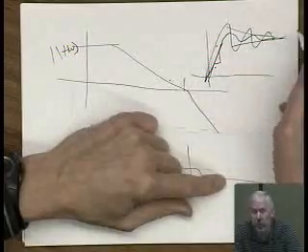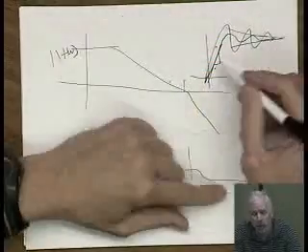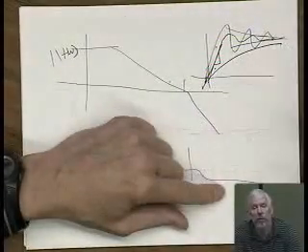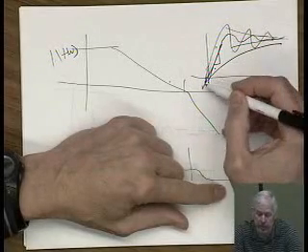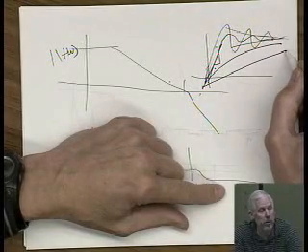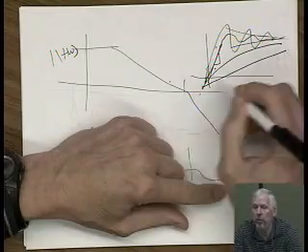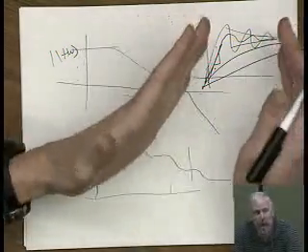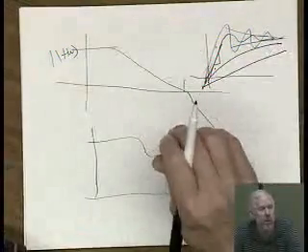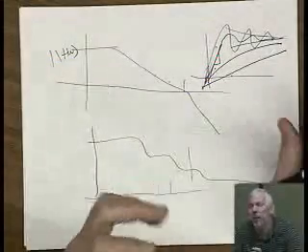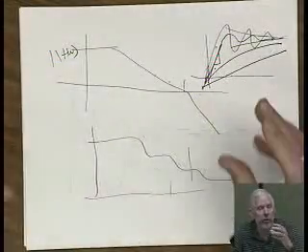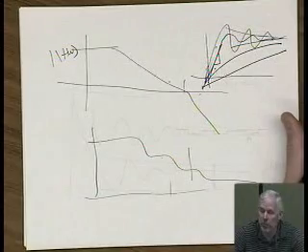Is it rippling a lot like this? That means your phase margin's probably too small. If it's coming up really slowly, maybe your phase margin's too large. If it's slewing really slowly, maybe your slew rate's too small. You've got to put some more effort into that. So look at the actual time response and see what's going on. Then towards the end, start using the test benches, like I say, for small amounts of tweaking.